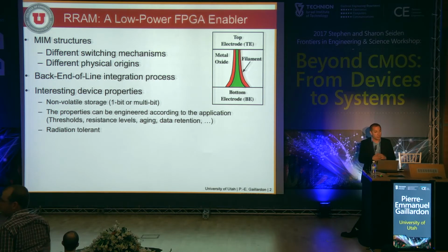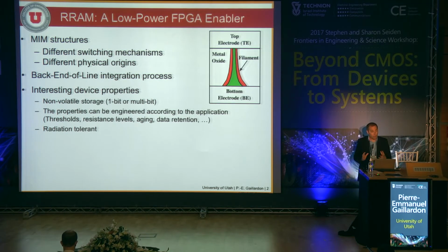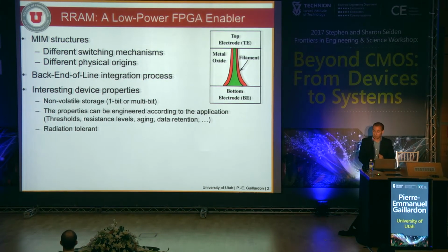Of course, everybody is talking about flash replacement, you know, large density, low power, low write power, and so on. But a very interesting thing is that you can engineer more or less all the properties of these devices. Properties being set and reset voltages, being the resistance windows depending on the energy, as Johannes presented. So you have really a lot of freedom to make some great trade-offs with such kind of devices.